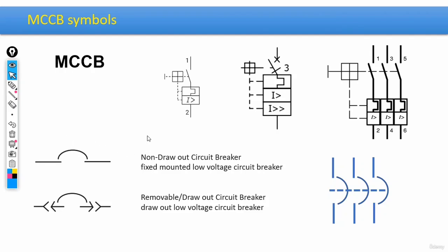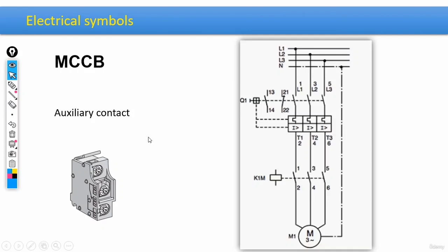Moving on, guys, there are some auxiliary features to these types of breakers. For example, MCCB breakers have auxiliary contacts. All right, let me try to give you a further elaboration on this. Let's say, for example, the switch is on here. Let me write it down. In this case, the normally open contacts that we have would be closed, and exactly in reverse, the normally closed ones would be opened. And basically this could be counted as an auxiliary feature that we have in such breakers.